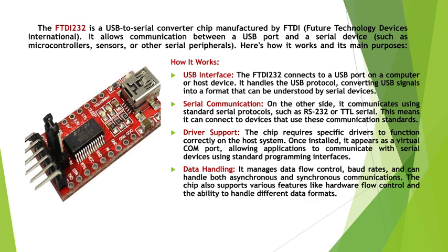Driver support. The chip requires specific drivers to function correctly on the host system. Once installed, it appears as a virtual COM port, allowing applications to communicate with serial devices using standard programming interfaces. Data handling. It manages data flow control, baud rates, and can handle both asynchronous and synchronous communications. The chip also supports various features like hardware flow control and the ability to handle different data formats.